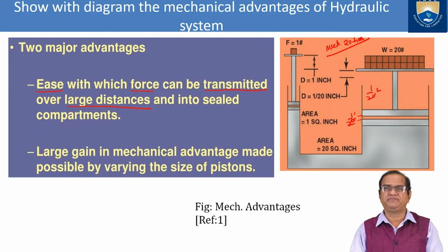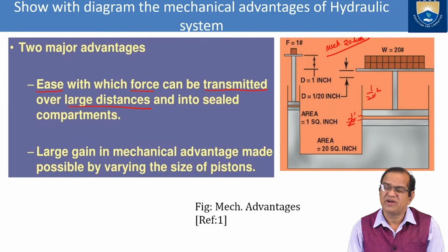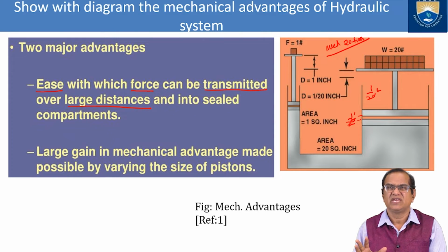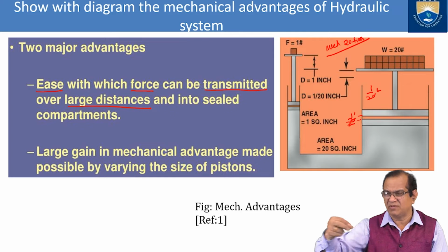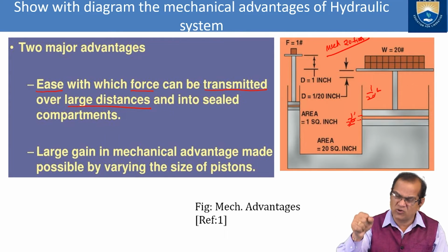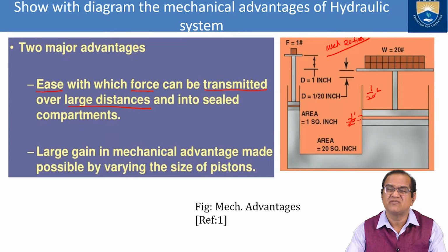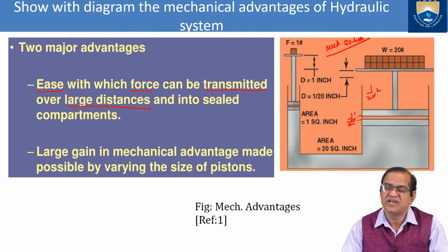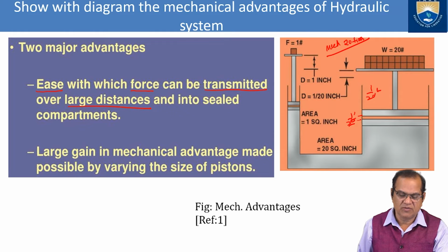Also, it has ease of operation, very smooth. If you have push-pull rods and mechanical linkages, they give a lot of noise and a lot of force has to be applied, and this much advantage is very difficult to get. So that is the first and foremost benefit, called the mechanical advantage.